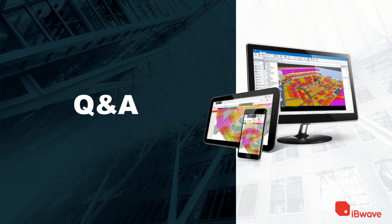And then it's going to also depend on whether we're looking at a network which is primarily used for roaming from the public cellular network on a phone, or if it's a purely private network. And both of those will have implications about which parts of the building you need to cover, as well as the radio side of this. Obviously, if it's a pure private network, you also have the other architectural elements like the core network to think about, and how everything interacts.